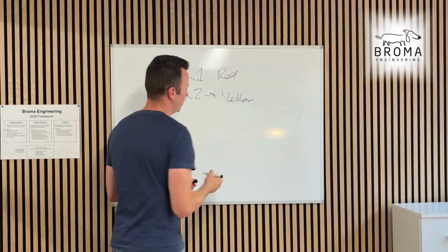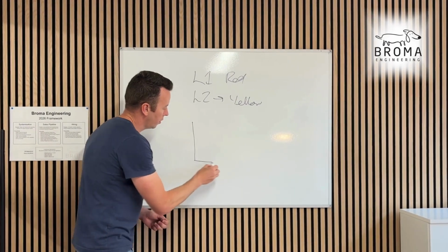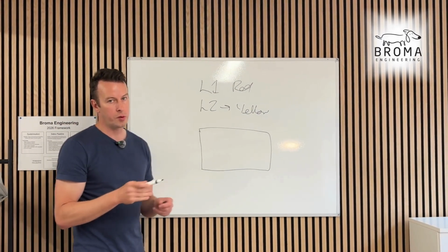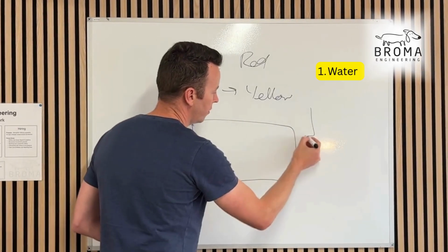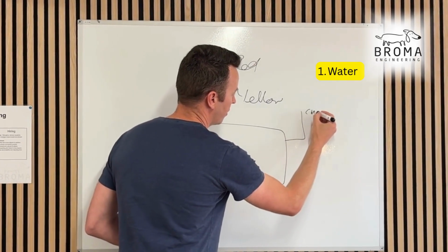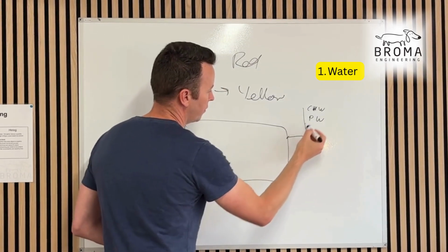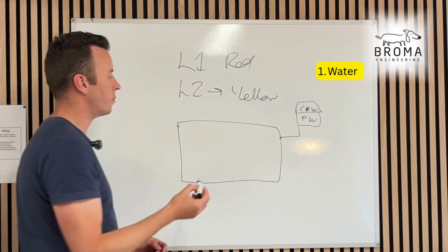And this is installation. Now it's already set in place, so all we're doing really, now, again, think of it as a black box. If you're just thinking from a process point of view, everything's a black box. And this is an AHU. What have we got coming into it? We either have chilled water or processed water. Okay, depending on if it's evaporative. Chilled water if it's a chilled water system. Processed water if it's an evaporative system.